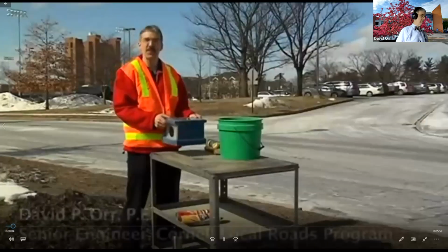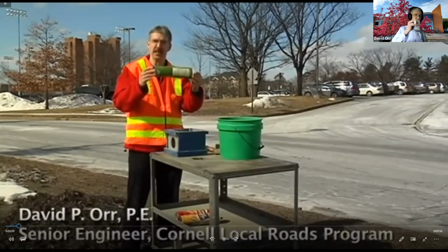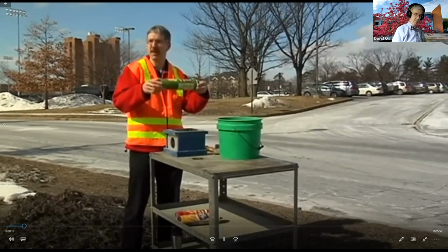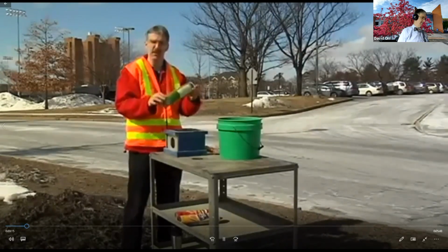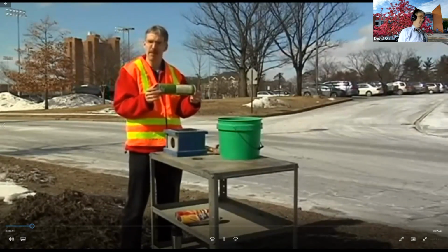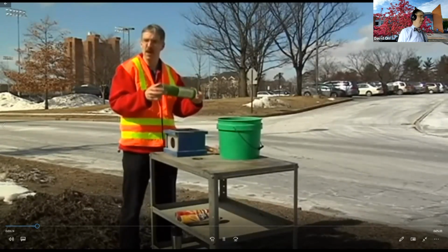And this is a demo that we did on culvert installation using a potato chip can that should illustrate the issues for any time you're installing flexible and even concrete pipe. Okay, in this demonstration we're actually going to build a culvert pipe out of a can of potato chips. This can of potato chips is an awful lot like flexible culvert pipes made of plastic or corrugated metals. Obviously not strong enough to support my weight, but if we backfill them properly, it will support my weight, same way that a culvert pipe will support the weight of a dump truck.